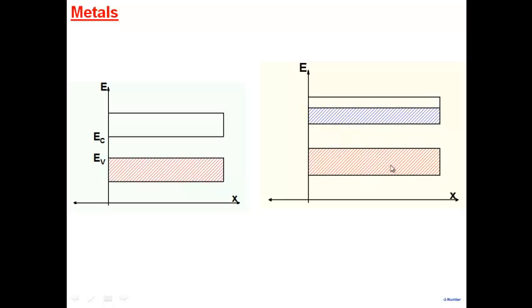On the other hand, here, this band will not carry current, but this one is partially full and will carry current. So a metal will keep on conducting, right? That's the nature of the metal. So you see that in a metal, all these electrons in this partially filled band are the ones which are of importance. They carry current. So in a metal, I don't need to take an electron and promote it to the conduction band, and thereby create an electron here and a hole. Electrons exist which can carry current right away. So the picture of a metal is different.